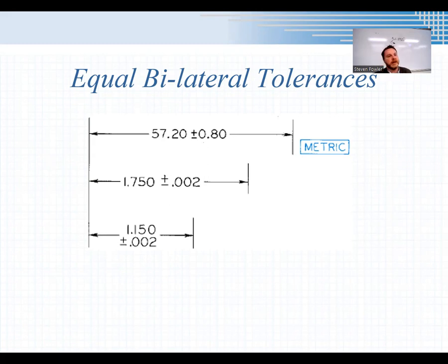Tolerances then would specify to anybody I'm trying to communicate with, here's how you make this cap so it fits on this marker, and here's how much above or below you can go. And again, there are a variety of ways you can do this. This is kind of the most common. You call out the basic dimension in the middle and say it can be this amount above or below, and still be acceptable.